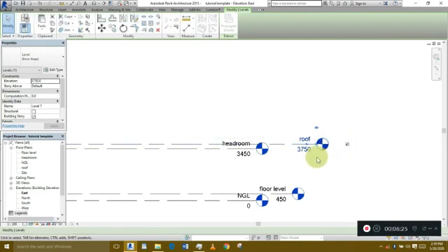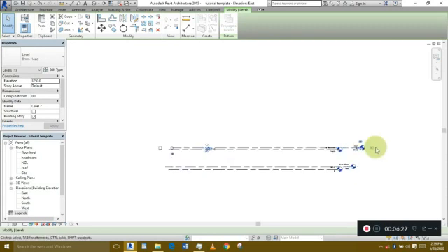Now we have created levels. This is how you create levels in Revit. If you have an upper floor, you can still LL 150 for your concrete slab. Then you go again, headroom 3000, and it continues like that. If you look at this place, you see we have floor level, headroom, natural ground level, roof, site. Site is the ground itself.